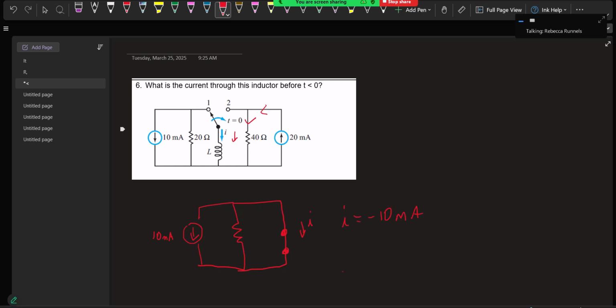because we know the current is going here, current's going here. Is there any possibility that some of this current is going this way? Or do we know that it all has to go this way? The answer is we know it all has to go to the right because we have 20 milliamps here, so we have 20 milliamps here, because it can't go that way. So we have 20 milliamps coming down this way. And if any of that 20 milliamps went in this direction, there wouldn't be enough for there to be 20 milliamps here, which there has to be.